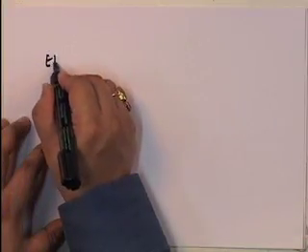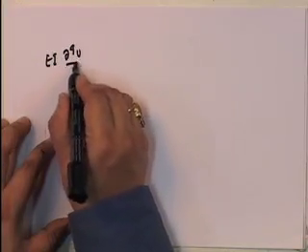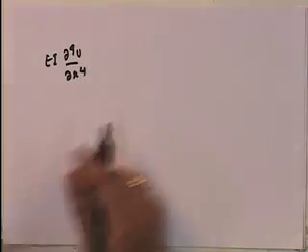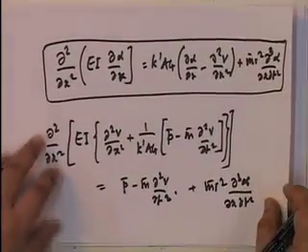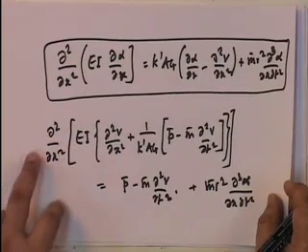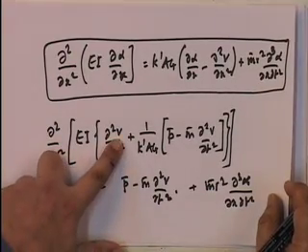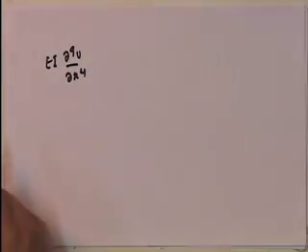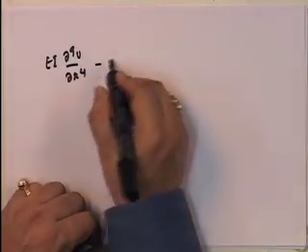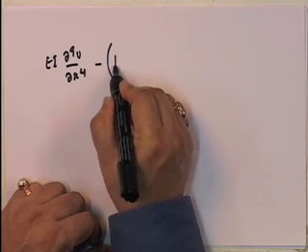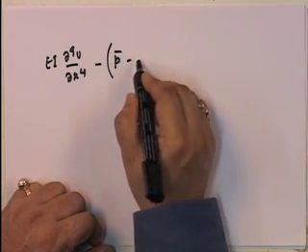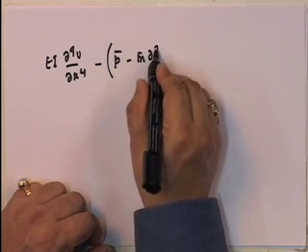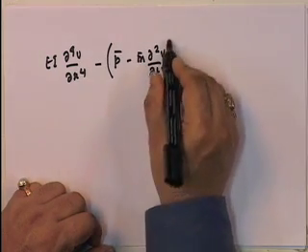I will just write the final equation, and I will explain what all of those terms are. There is one term EI ∂⁴V/∂x⁴. That comes from the double differentiation, and EI is a constant, so this is the fourth order term that comes. Then we have minus (p bar minus m bar ∂²V/∂t²).